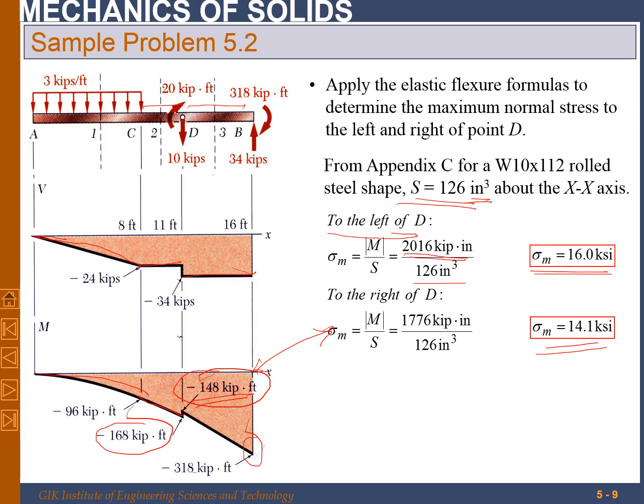In order to draw the shear force and bending moment diagram, we have to take a section just before and after the load application point and draw the free body diagram for that section, considering the sign convention. Then by applying the static equilibrium condition, we can find the value of internal shear force and bending moment. And we can use the bending moment to find stresses by applying the elastic flexure formula.